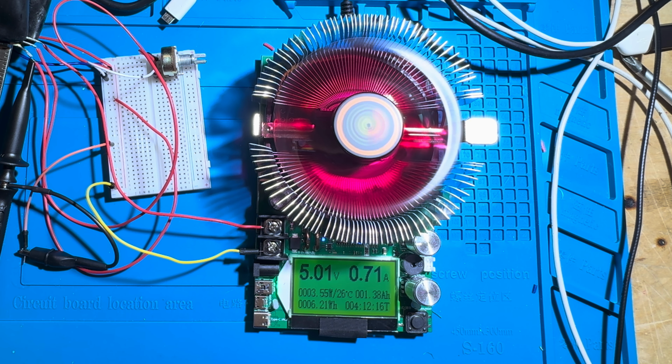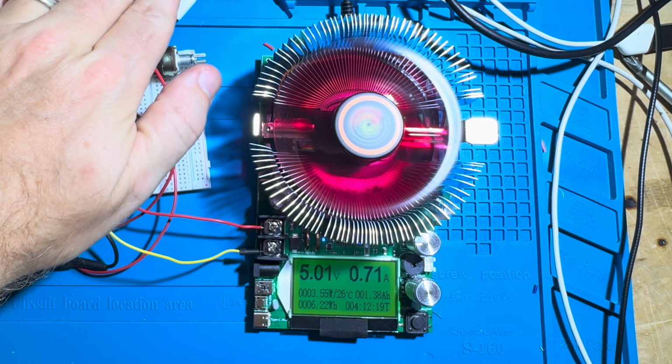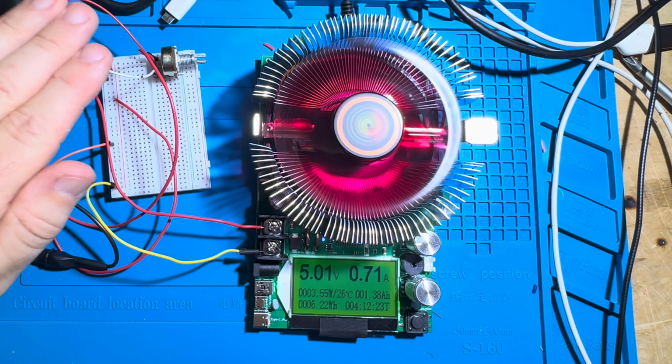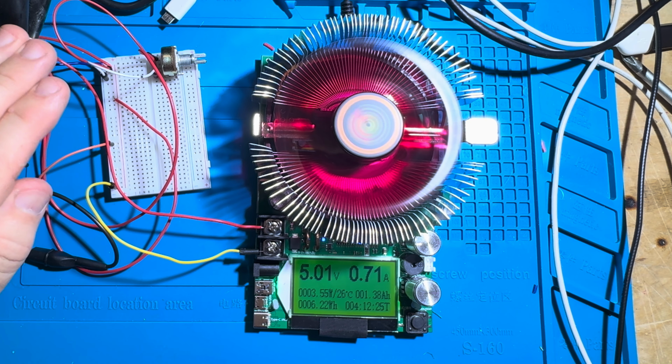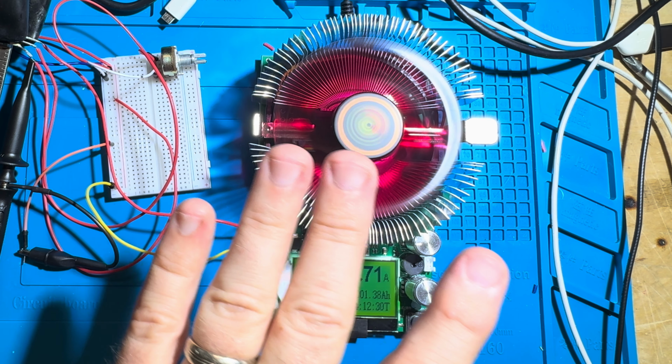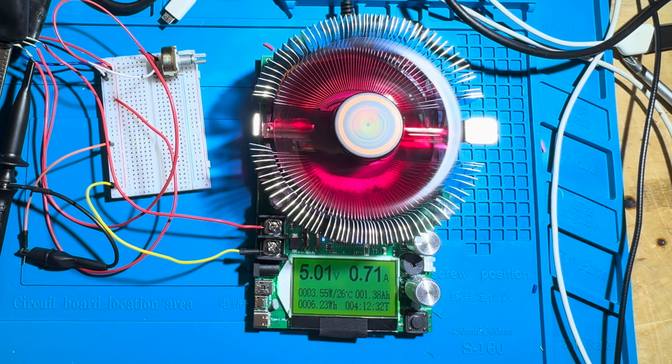So that's a relatively small change in gate voltage resulting in a significant difference in the amperage across our load. So this potentiometer setup here is highly sensitive to the gate voltage. So very, very small changes in gate voltage can drive large changes in the voltage and the current through our load. So this is kind of a sensitive, fiddly system. Like you would never want to use this in real life.